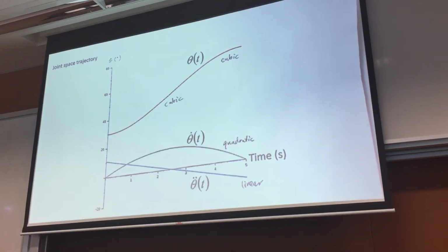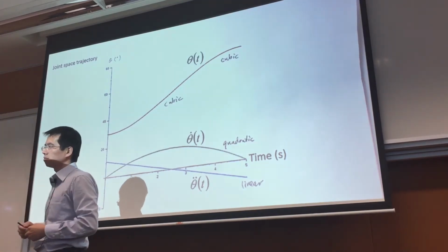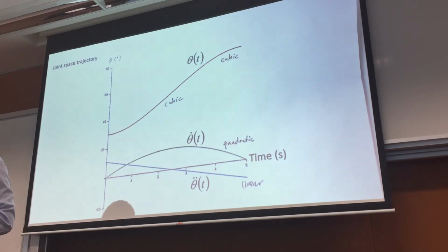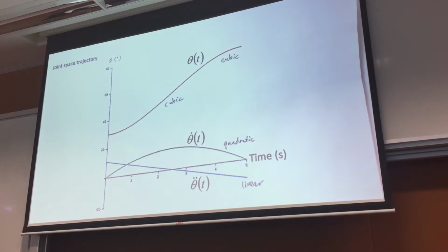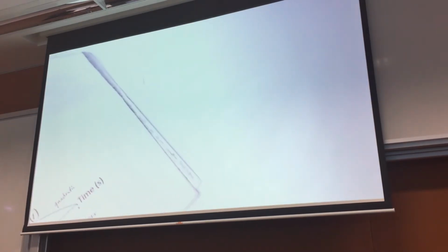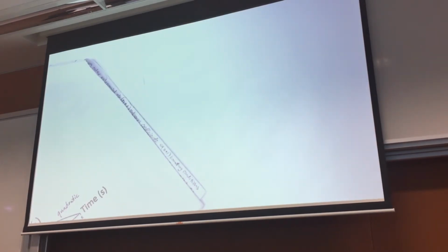When you look at this, can you tell me if this linkage is accelerating or decelerating? It's decelerating. If you don't sketch it out, it's harder to see. But from the equation, if you look at your acceleration equation, acceleration is equal to 10.8 minus 4.32 t.